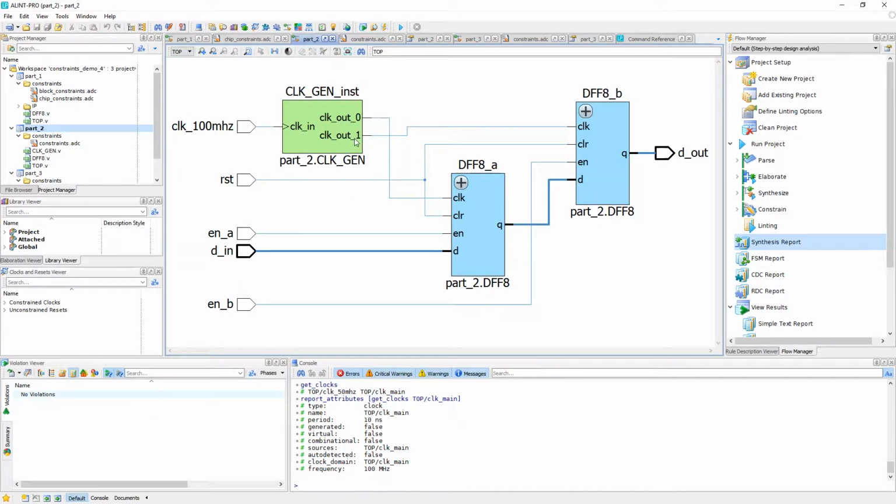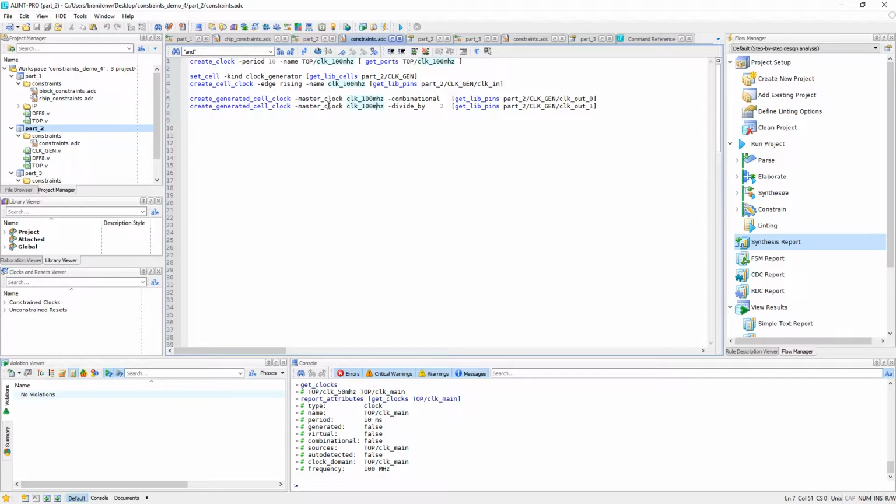In this example, both clocks are controlled by a master clock, and the constraints file shows constraints only for our clock generator. Currently, one clock passes the master clock through, while the second clock divides the master clock by 2. Despite no constraints for clock groups currently written, we can see from our violations that no clock domain crossing is detected. This is because of our default domain detection mode, considering master shared clocks with division by 2 to some n power to be of the same domain.